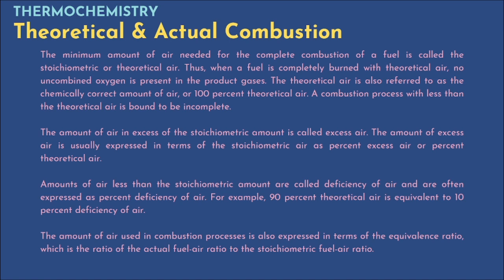The amount of excess air is usually expressed in terms of stoichiometric air as percent excess air or percent theoretical air. Amounts of air less than the stoichiometric amount are called deficiency of air and are often expressed as percent deficiency of air. For example, 90% theoretical air is equivalent to 10% deficiency of air. The amount of air used in combustion processes is also expressed in terms of the equivalence ratio, which is the ratio of the actual fuel-air ratio to the stoichiometric fuel-air ratio.